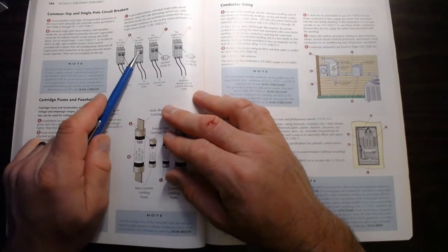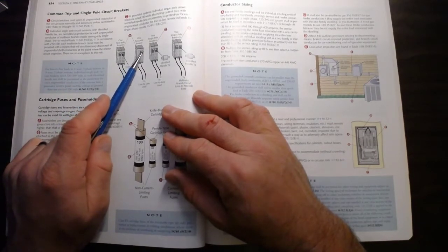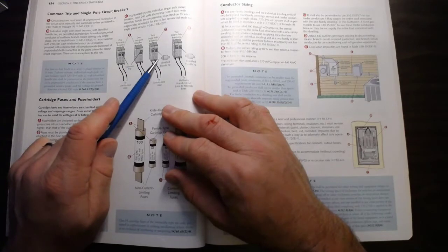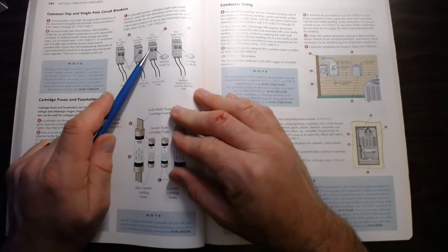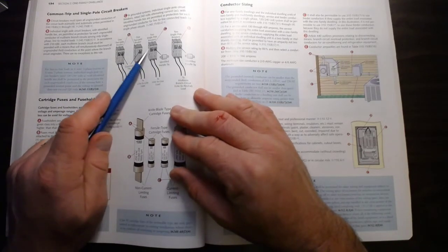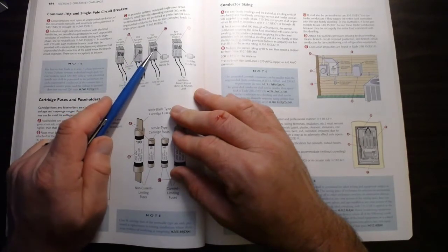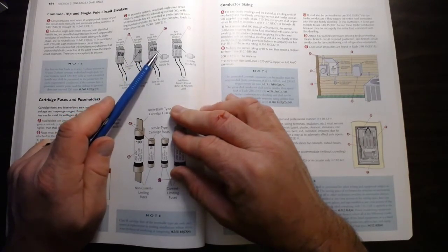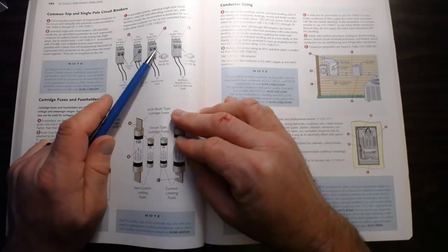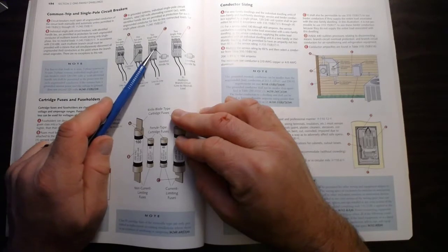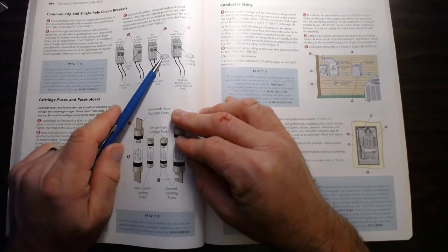In this case, this manufacturer has one throw but internally it's a 2-pole breaker and it has a common trip internally. I have seen all kinds of variations here where they've stuck a nail through a paper clip and they don't work because one side will trip and the other side will remain on and burn the equipment up or be unsafe. So it has to be a factory installed common throw device.